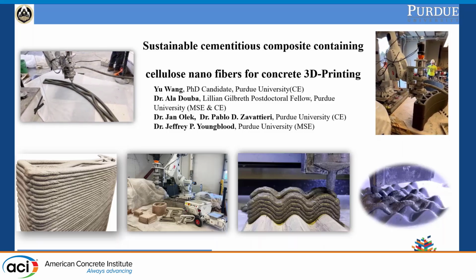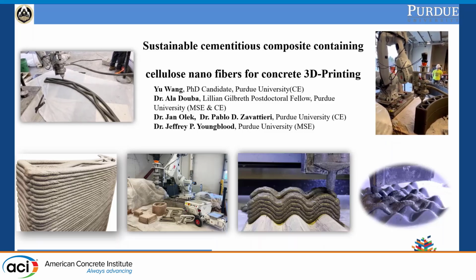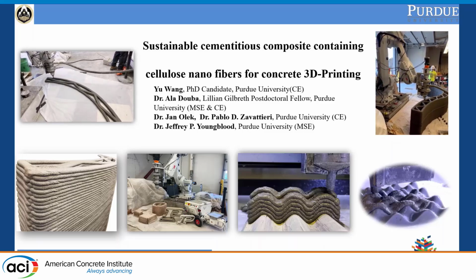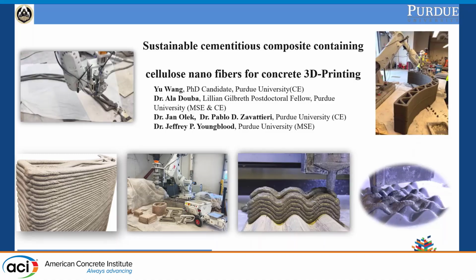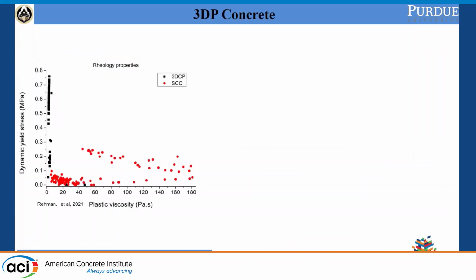Today I'm going to talk about our recent work on cellulose nanofiber. We are also trying to study the rheology, compressive strength, and a little bit of cement hydration on that. So I'm going to start with this slide.